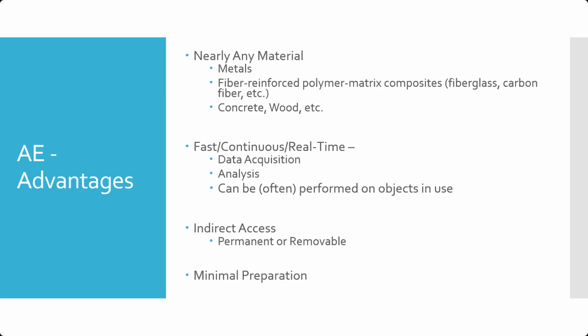You'd touch it to motor frames, bearing housings, different pieces of machinery, and it would be able to capture an acoustic signal based on the vibrations that were transmitted into the little probe. And minimal preparation. If it's installed permanently, there's really no preparation. It's part of the installation or build process.